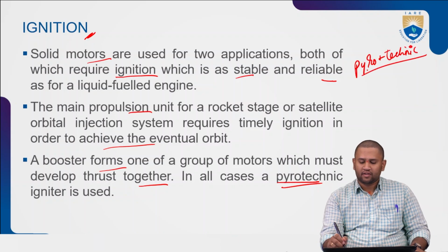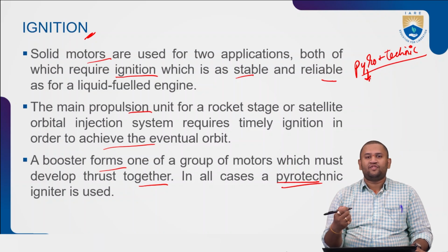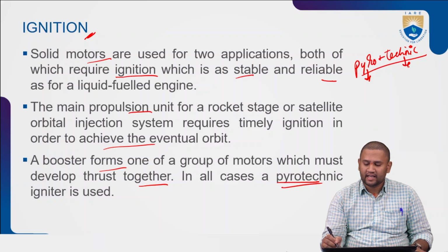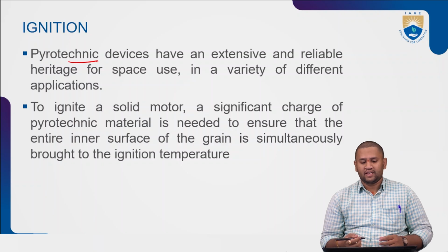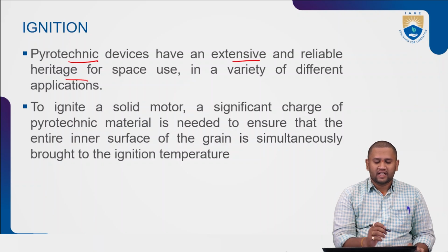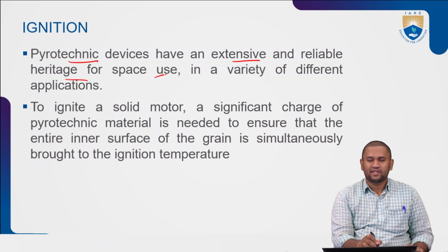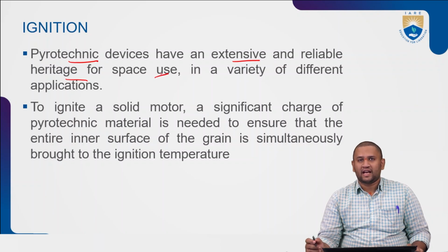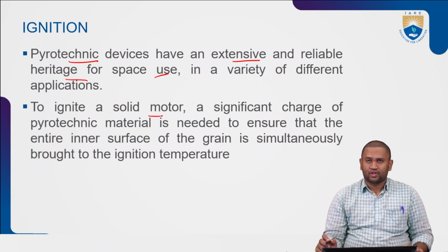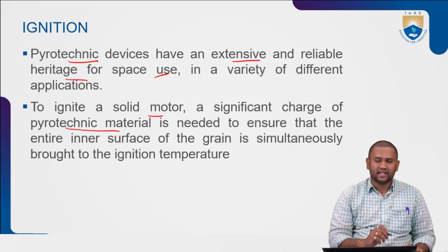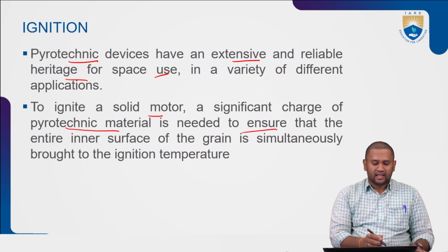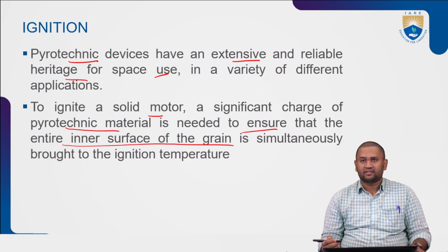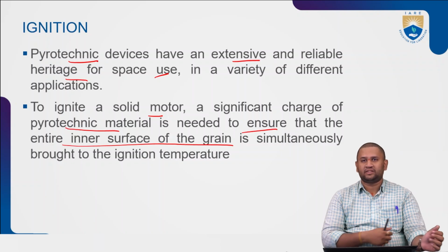What do you mean by pyro? It is nothing but the study of combustion, or the study of combustion fuel, and technique means methods. Now, pyrotechnic devices have an extensive as well as reliable heritage, particularly for space use and in a variety of different applications. To ignite a solid rocket motor, a significant charge of pyrotechnic material, a small explosive material, is needed to ensure that the entire inner surface of the grain is simultaneously brought to the ignition temperature.